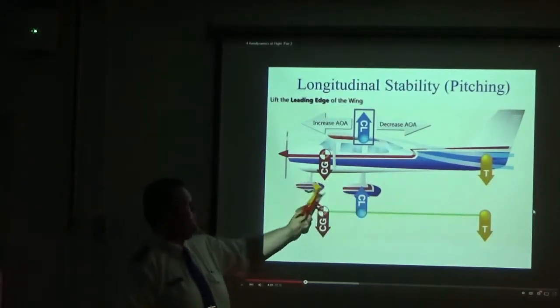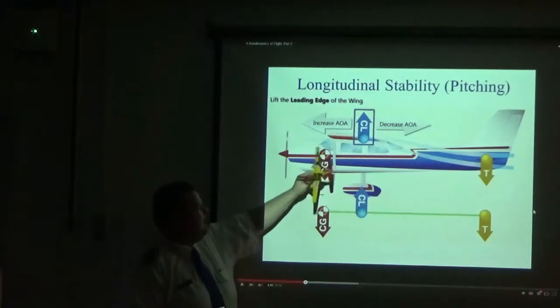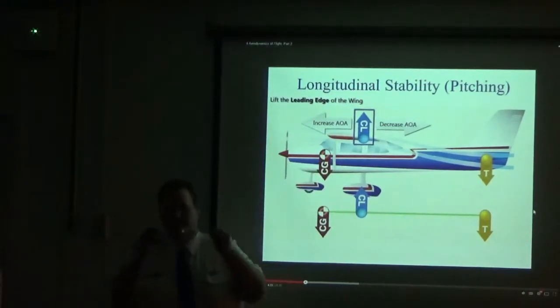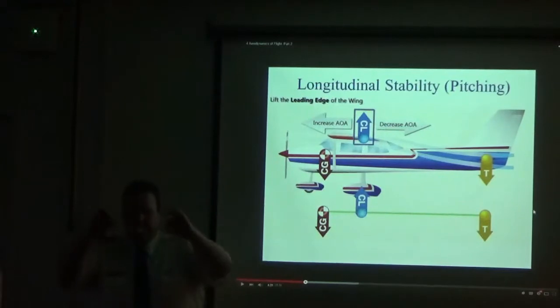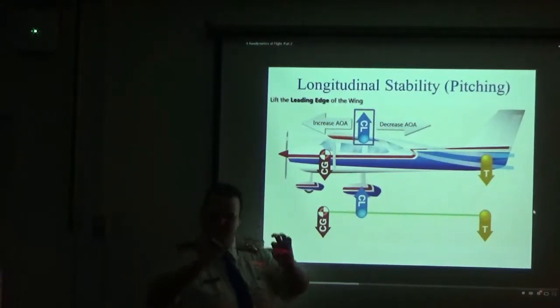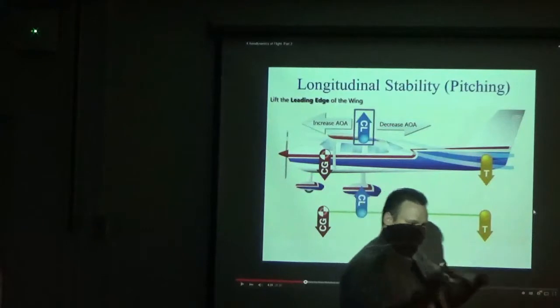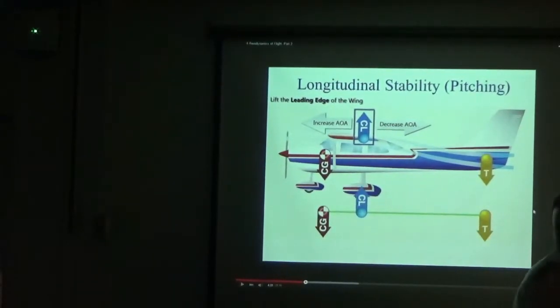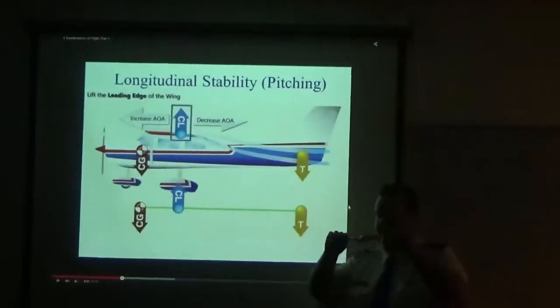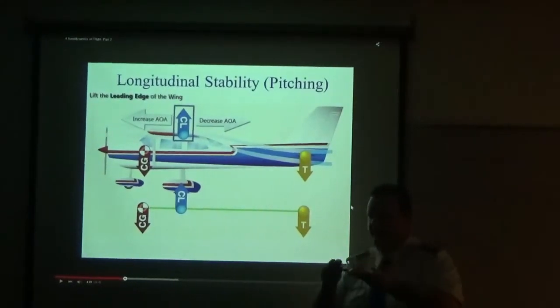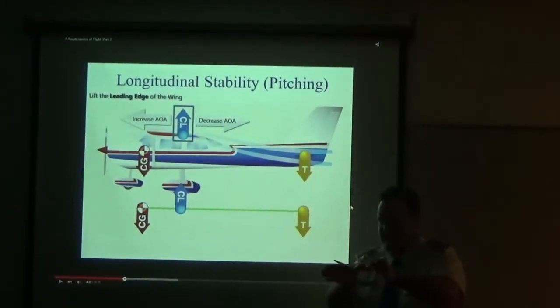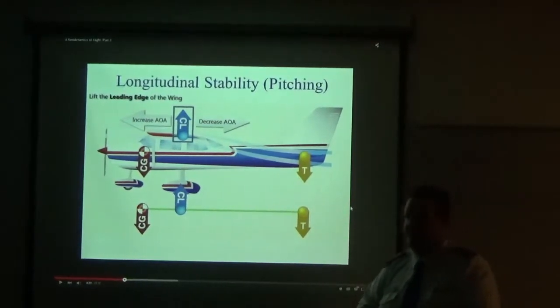Another dangerous thing about being overweight while flying is the wings. If you're flying and you're overweight, the wings have some flexibility. It's designed that way to help catch the air and also keep you aloft. If it was just a solid structure, it would most likely snap. So it needs to have that flexibility. Well, if you get into some type of turbulence or bumpiness, and you're overweight and it overstresses the aircraft beyond its safety measures, it can easily just snap the wings right off, which is also a very dangerous thing about being overweight.